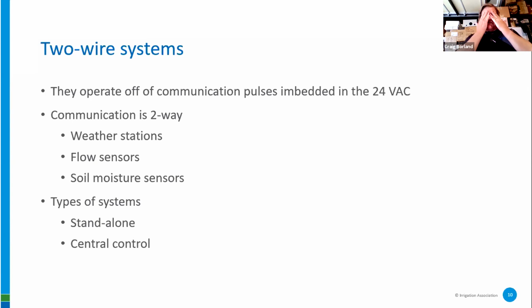That's not what I'm expecting. That's way too much. Shut that zone valve down, and let's go to the next zone on this system. Zone 15 turns on, flows good. It continues on its way, but it sends an alarm back to the controller saying zone 14 has a high flow condition. I skipped it.